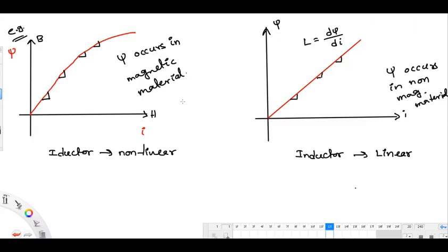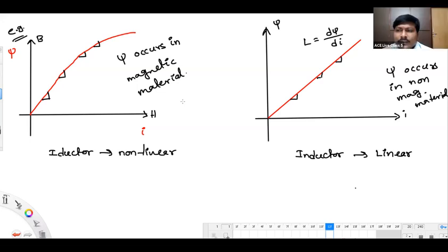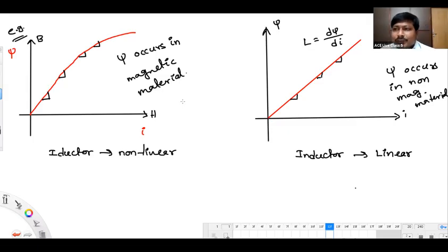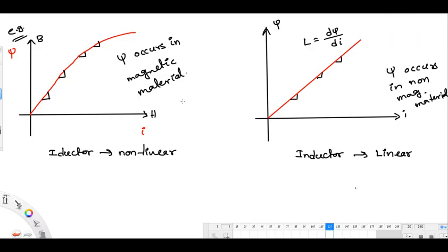And sir, one more thing: you mentioned that ACSR would have a skin effect that lies between that of solid and AC. Yes, because of the steel. The steel doesn't carry any current, so the effective area reduces. A magnetic material we have introduced, so μr was increased. So we can also say by this logic, sir, that the effective area gets reduced. Okay, sir.